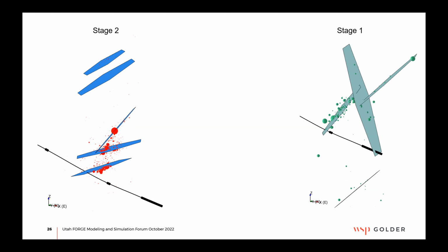I would say an honest viewpoint is, our coring results have been mixed, just based on the difficulty between the depth, the temperature, and the rock type. But we're also looking at ways to do early reservoir testing between A and B once that happens. This is still in the planning phase, and I'm not committing to anything here, but we would use some of our DTS or DAS fibers in the open holes or inside the holes themselves, when we do some of these flow tests between the two wells, to look for areas where we see flow entering or exiting the respective well. That should hopefully give us a lot of insight into this actual fracturing process. That, I think, will be really illustrative of this.